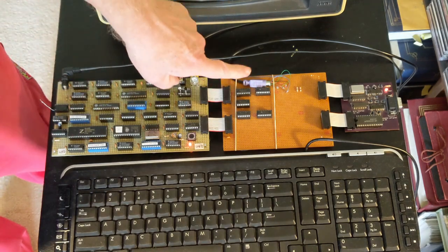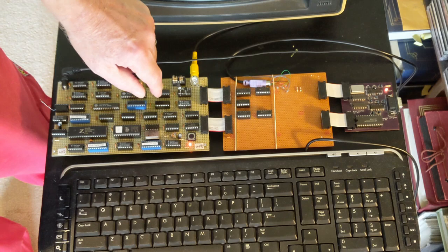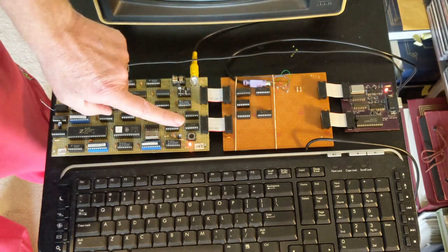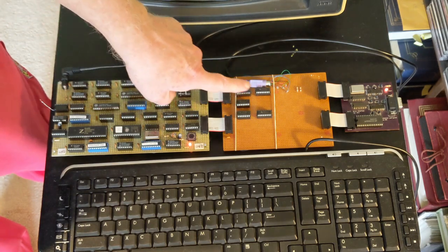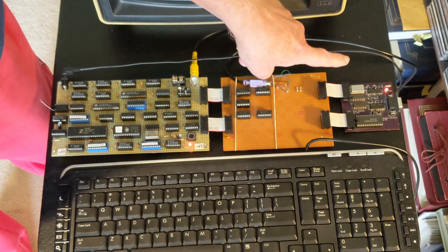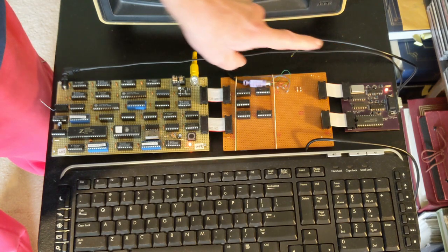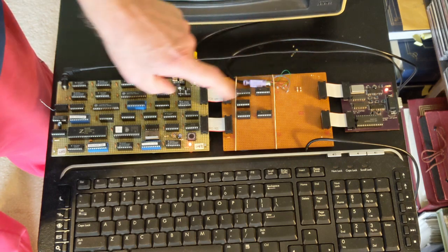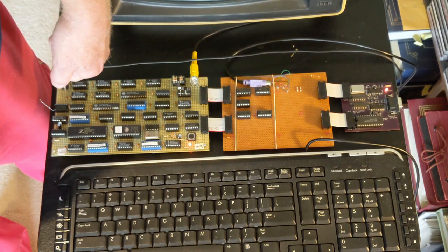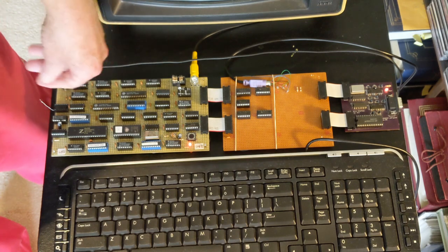This is the PS-2 keyboard interface. I didn't have a proper socket, so I just wrapped wires around the pins of the keyboard plug. But the hardware is very simple, as you can see. This is an optional serial port used for loading programs into the system. It's not needed for console input and output as it is in the single board Z80 computer.